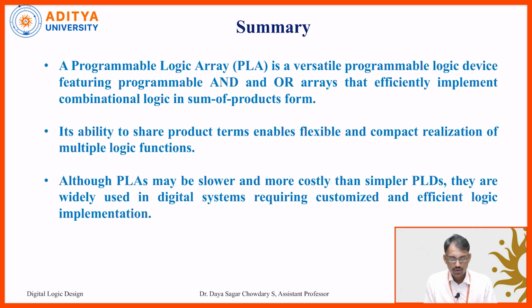Coming to the summary, a PLA, simply called programmable logic array, is a versatile programmable logic device featuring programmable AND and OR arrays that efficiently implement combinational logic in SOP form. Its ability to share product terms enables flexible and compact realization of multiple logic functions. Although PLAs may be slower and more costly than simpler PLDs, they are widely used in digital systems requiring customized and efficient logic implementation.